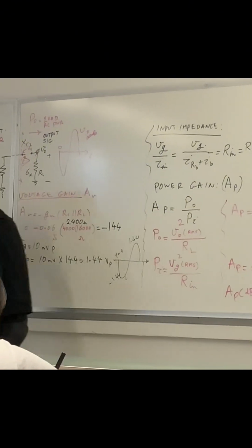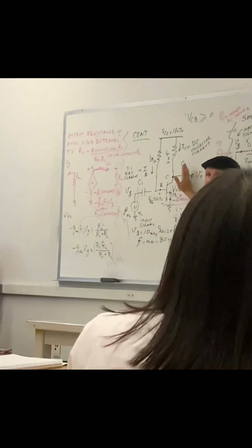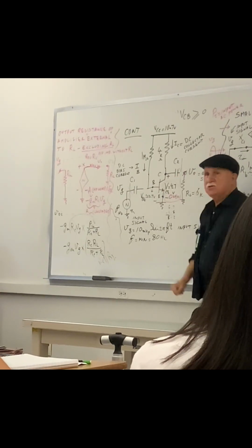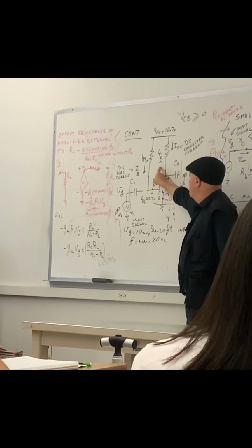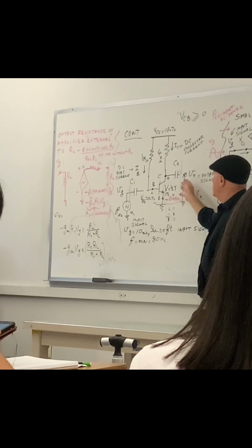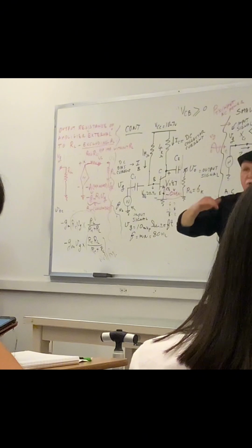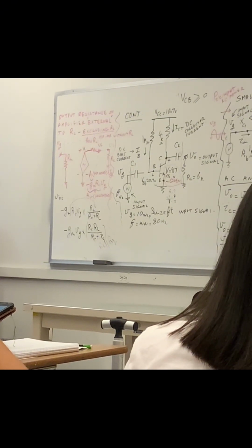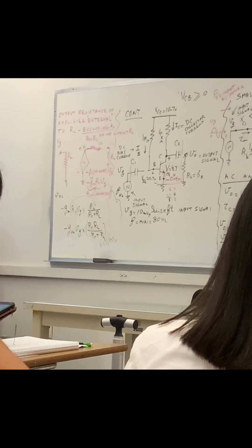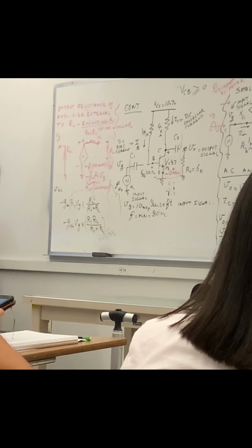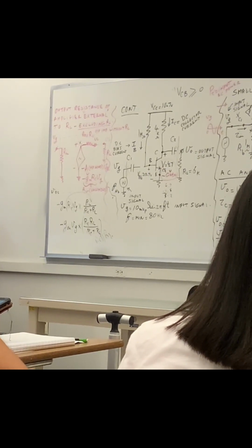This is on its own, the load is 240 without the RL. Yeah, if you delete this, GM times 4K will be 240. But when the coupling comes in, it drops to 144. That's the problem with this amplifier, that you have a high output impedance, 4K is too high, and when you put the loads, boom, it drops.